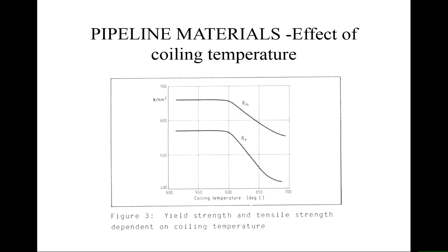And so this is a productivity question. If the strip is coming out of a strip mill very hot, do you coil it up straight away and get a lower strength, or do you allow it to cool a bit and then coil it up? That's the sort of question that you have to ask. But material can be delivered with the right sort of properties.